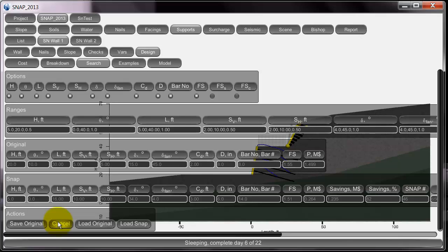So it figures out all of these things, and then it says, like, when I have a low batter angle and I increase the nail length, or I have a low inclination angle and I increase the length of the nail, that has a different effect on the factor of safety than if I had a short nail, or the same length of nail with a large inclination angle. So it's generating all of these theories and trying to figure out where the causal relationships are.